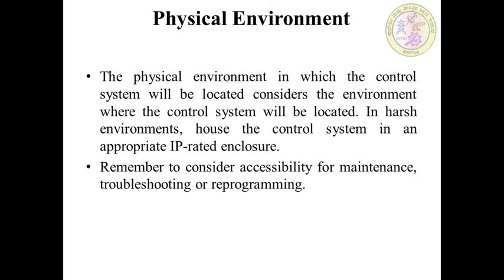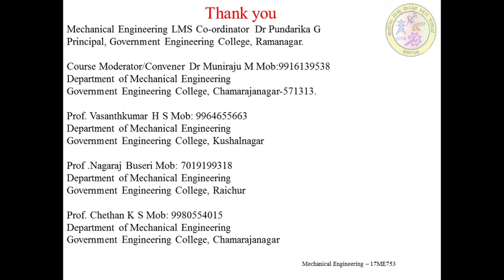And as for the physical environment, consider the environment where the control system will be located. In a harsh environment, house the control system in an appropriate IP rated enclosure. Remember to consider accessibility for machine maintenance, troubleshooting the overall system, or reprogramming conditions.